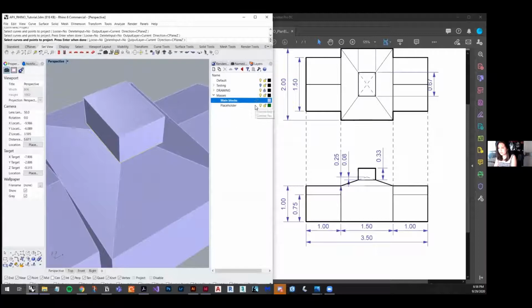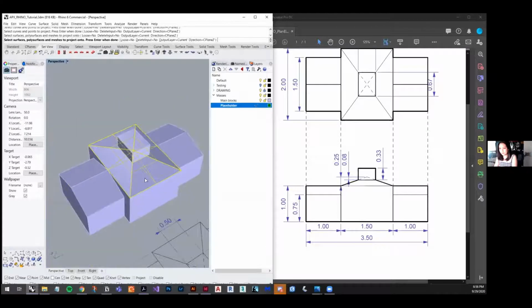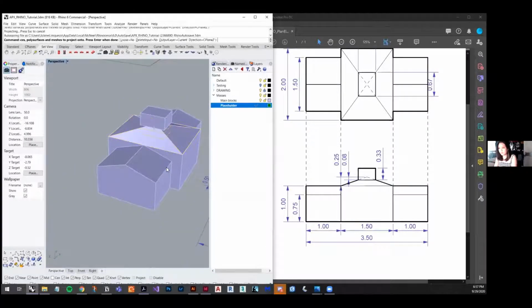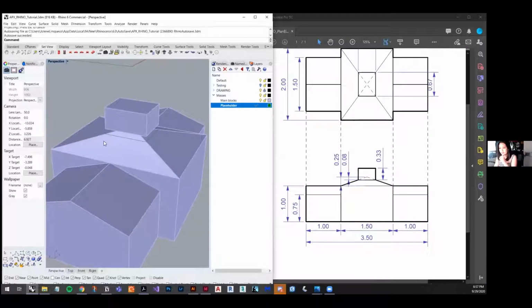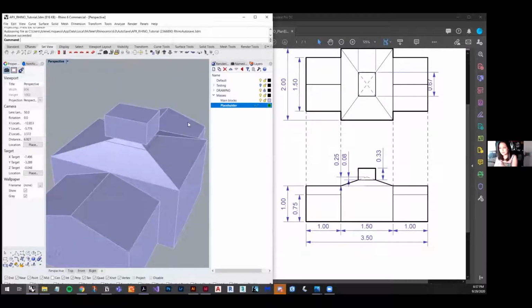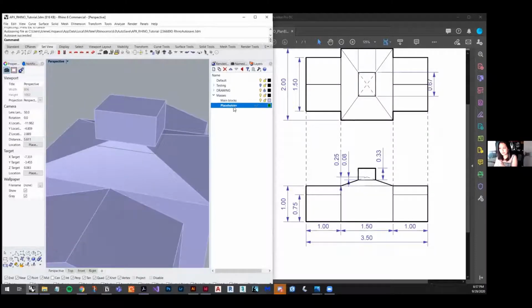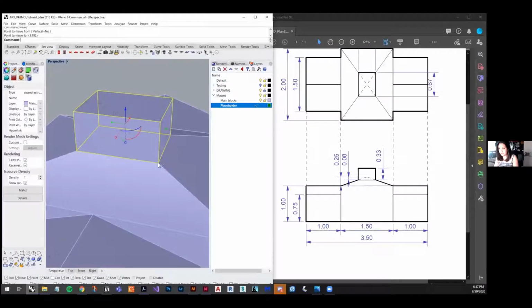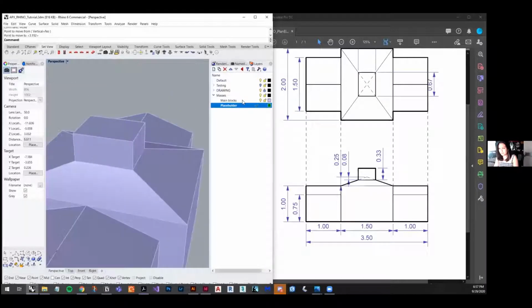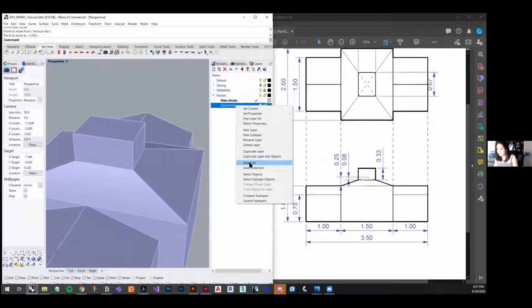We're going to use placeholder, and then this is the surface that we want to project it onto, because we're going to move it downwards. Press enter, and as you can see, it made these curves along the whole entire poly surface. This is the reason why I did placeholder, because once we move this down over here, it's going to be a pain just to select all of those. So what we can do is select all. Oh wait, no, sorry. We're just going to delete layer. I don't know why I did that. So we can just delete layer.